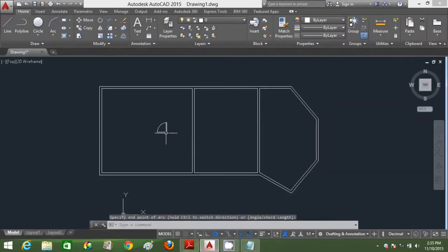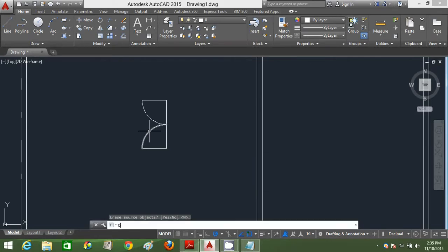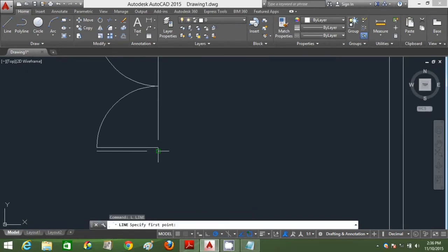So I guess my arc goes wrongly, so I'm just gonna draw the correct arc corresponding to the arc shown in the floor plan layout. So I'm just going to draw the 900 mm lines first and press A, enter, type C, enter, and click one start point and click to the other end point. So I'm just going to mirror this by typing MI, enter. MI, enter for mirror. Okay, I'm going to offset these two lines by 50 mm and close it.